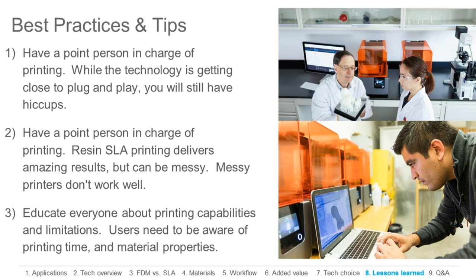Another thing is just trying to make a printer do what it's not designed to do. For example, I really like my MarkForged printers. However, if I need an airtight model, they can't do it. I have some small cases that are getting printed right now for medical equipment that will be used in the field in India, and they need some of them to be basically waterproof. And an FDM printer just isn't going to do that. So don't try and force it. Find the right tool for the job. That's one of the reasons I have all the printers, is that each of them does something very well.